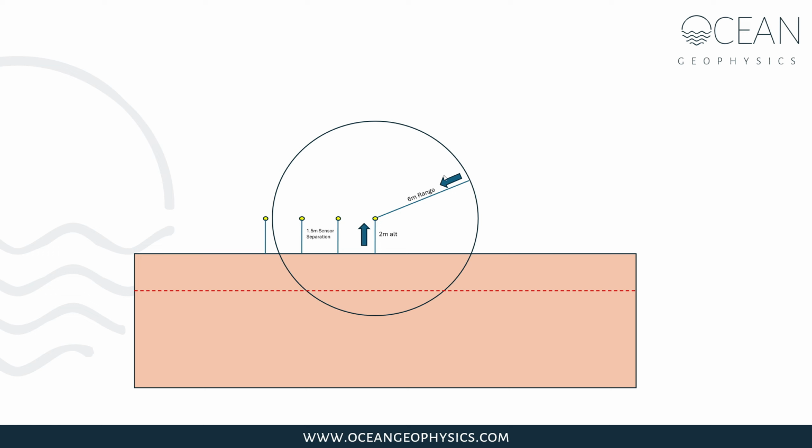So in our experience, the most sensible thing to do is come up with a sensible range. There is a reason why the larger UXO consultancies do not allow the spherical range to be changed, regardless of what is found in a surrogate items trial. Consultancies will state that the maximum spherical range you can use is 6 meters. You have to go and do a SIT trial. If your SIT trial shows that the target can be detected at 9 meters, they will not allow you to change this range. And this presentation is actually showing you the entire reason why this is so.